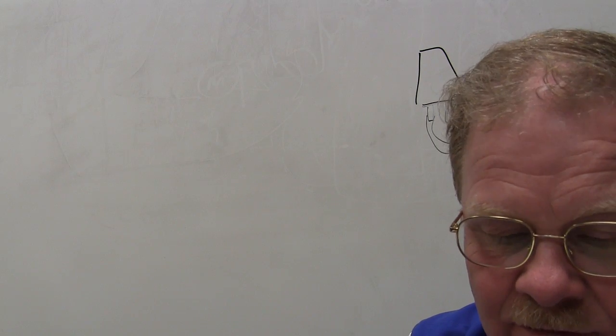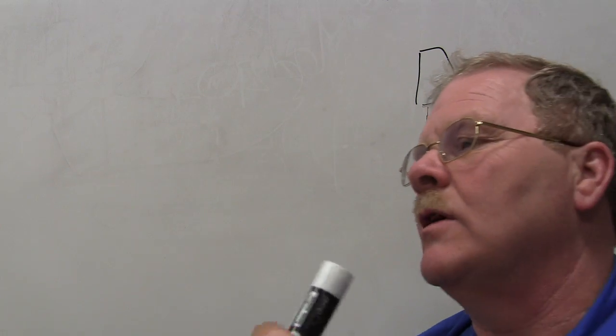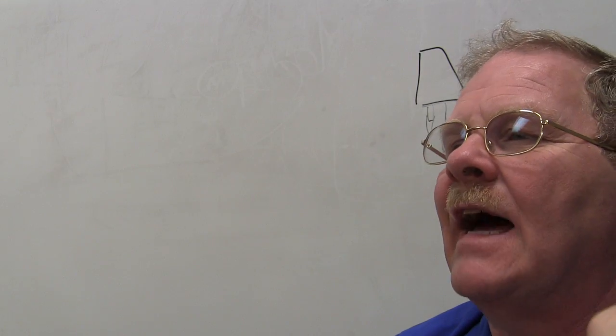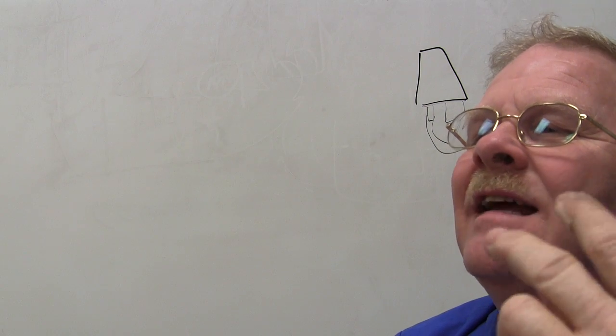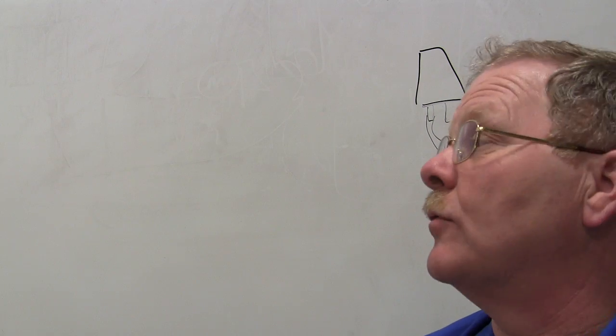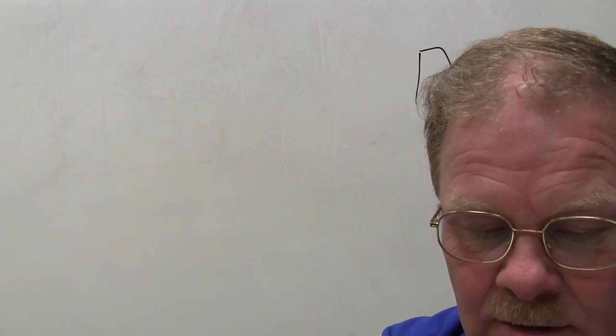But that's basically going to be B. That's going to be 15 inches of mercury, so it's a little higher than what's normal. What do you expect to see? What's a healthy engine got for vacuum at idle? 20 or 30? 18 to 22 is what you're looking for, and you'll see a green range on your vacuum gauge for that.